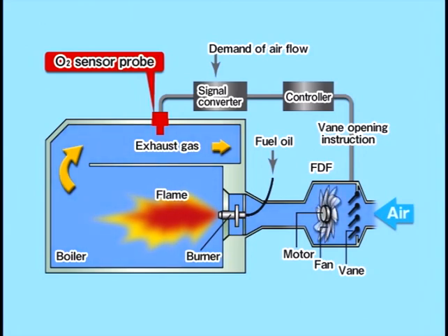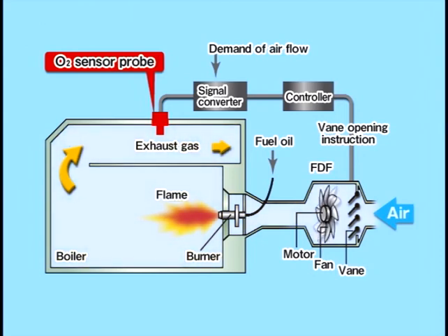The oxygen analyzer is an instrument used to measure combustion within the boiler. The boiler uses a forced draft fan, or FDF, to intake air for combustion. When FDF ventilation is reduced, incomplete fuel combustion occurs in the boiler, generating a large amount of dark smoke. Conversely, when ventilation exceeds recommended limits, heat loss occurs. The excess air takes heat with it as it is exhausted. Furthermore, excessive ventilation also increases NOx emissions.